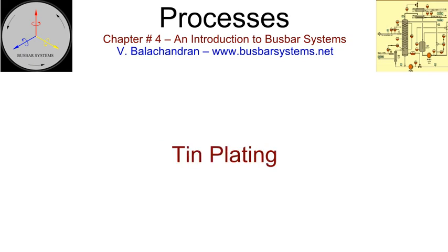Tin plating. Tin plating has been extensively used at the contact joint. There is also mounting evidence that tin plating of contacts leads to fretting, resulting in joint degradation. Further, tin forms an alloy with copper even at room temperature, rendering the joint brittle. Both these effects can result in higher contact resistance. Tin plating is inexpensive and many manufacturers carry out tinning of busbar for the entire length instead of just on mating surfaces of the tabs. Most of the sandwich bus manufacturers adopt this practice. Plating with lead tin alloy provides a shiny surface.